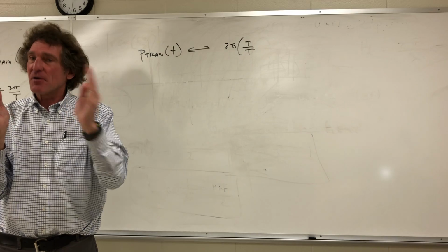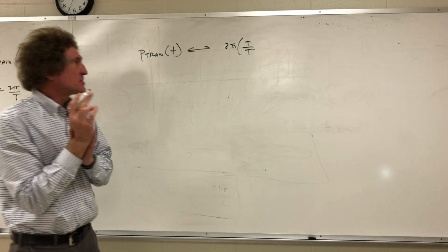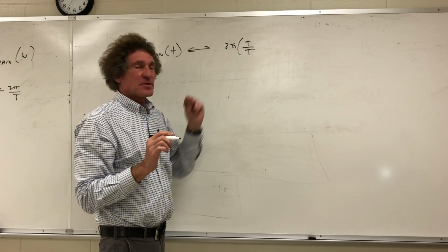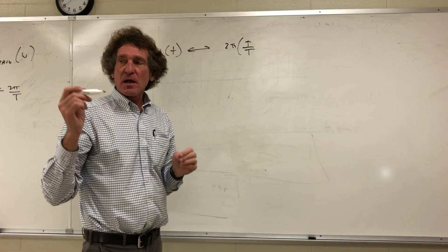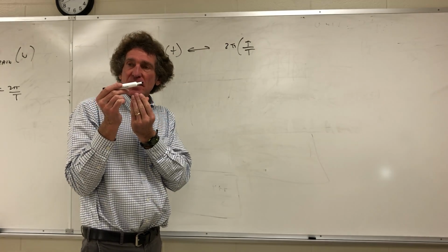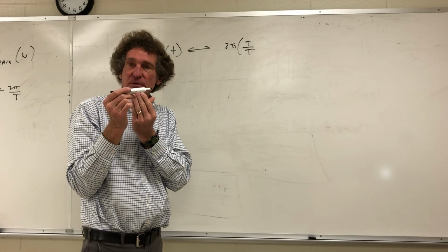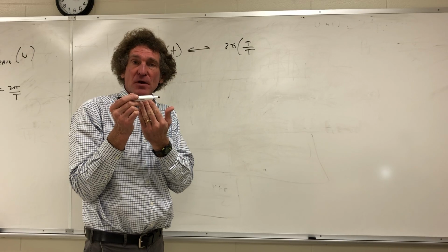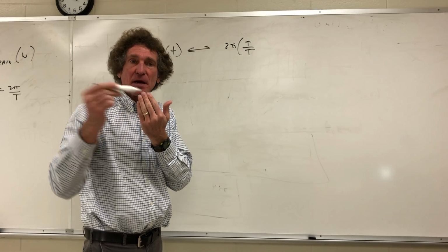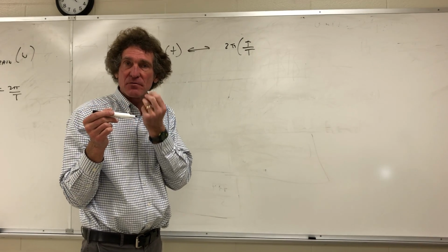It's just the PRI, right? I'm almost tempted to put PRF there, but I like tau over T because that's a duty cycle. That, in my mind, is something that's very important. A lot of radars have super small duty cycles because they want a tremendous range resolution. The downside is they lose their average power, so they need to collect an enormous amount of pulses with coherent processing to get real information.